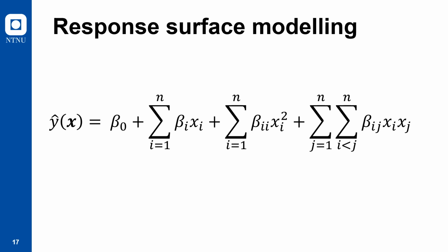Response surfaces are mathematical models constructed by doing least square regression. The idea is to create response surfaces of my objectives: the pressure recovery factor, the energy loss coefficient, and the draft tube volume. This will provide mathematical models of my objectives given as a function of my design parameters, which I can use for further discussion.